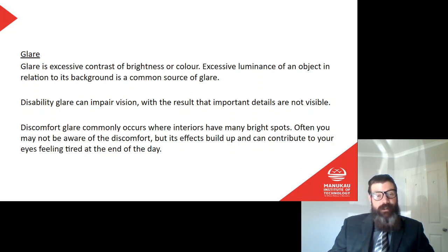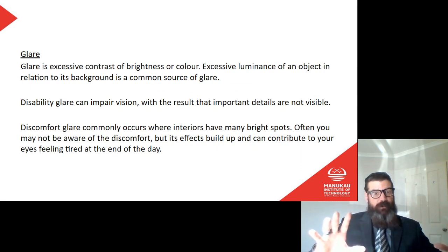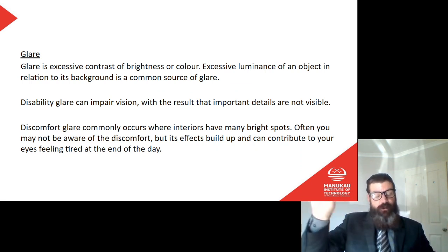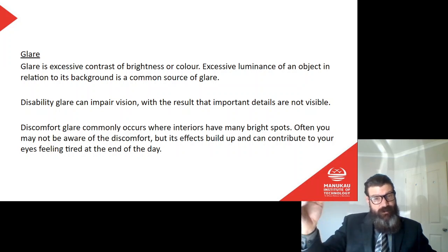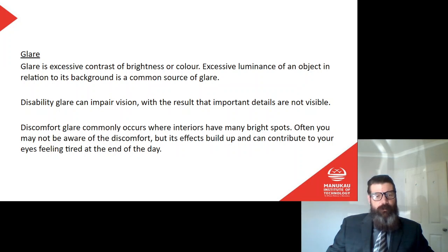However, the screen that I'm looking at in front of me and my desk is quite dark compared to that very bright light coming through that window, so that is quite uncomfortable. I would not say it's at the point of disability glare, although if I look directly in that direction, I can see this burning light coming straight off the windscreen of that car. As long as I'm focusing on what's in front of me, I'm not getting disabled by that glare, but it is uncomfortable discomfort. And that's the kind of glare that, as it says here, we might not notice as we go through our day, but it can make our eyes tired.